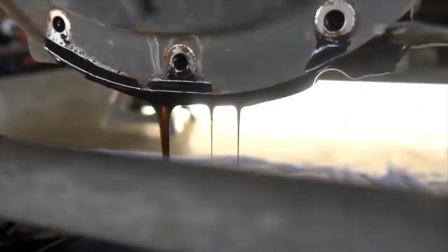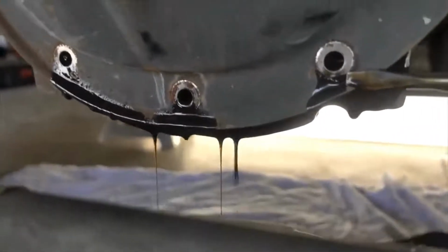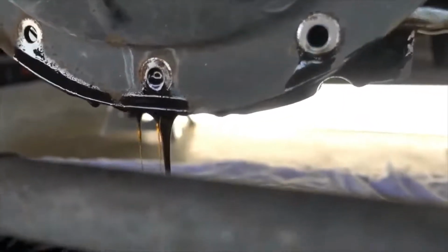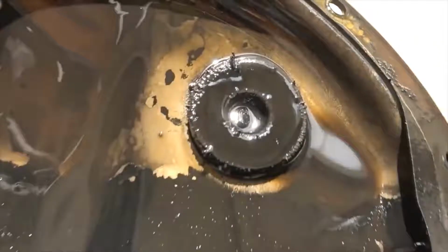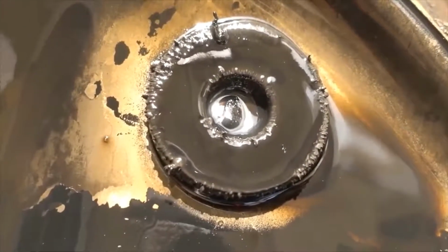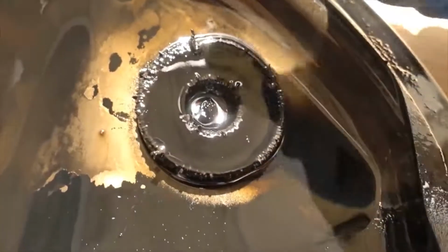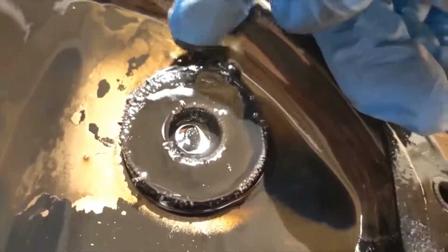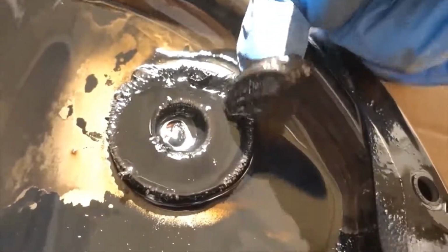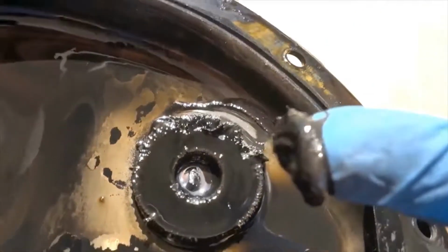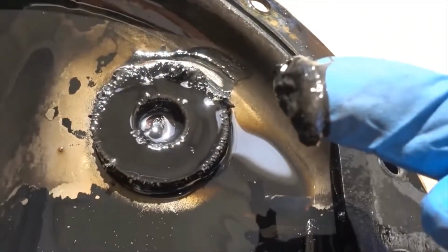Not servicing the LSD may cause the LSD to fail at some point because of gear failure or jamming inside the gears. Not only that, here we can see there's a magnet. This magnet is to filter the metal shavings inside the lubrication oil of the LSD. And since the LSD hasn't been serviced for 135,000 kilometers, we can see all the metal shavings built up inside.